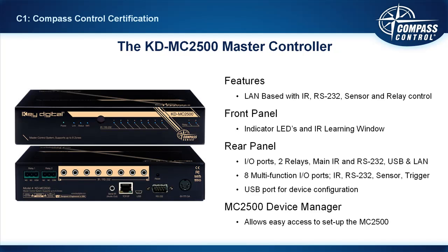The rear panel has the 2 relays, the 8 I/O ports, and these are multifunction I/O ports. They're going to offer bidirectional IR, two-way RS-232 with feedback, sensors being either audio, video, or voltage sensing, and they can also be used, these 8 I/O ports, as triggers to provide a voltage differential in order to trigger a subwoofer or maybe a distribution amplifier.